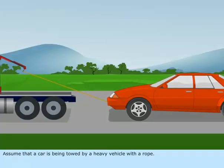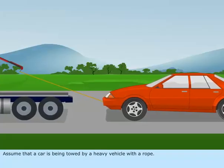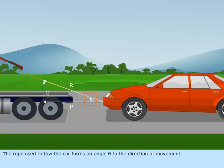Assume that a car is being towed by a heavy vehicle with a rope. The rope used to tow the car forms an angle theta to the direction of movement. The tensile stress R in the rope can be divided into two forces. Assume that P is the force acting in the direction of movement, and Q is the force at right angles to the direction of movement.